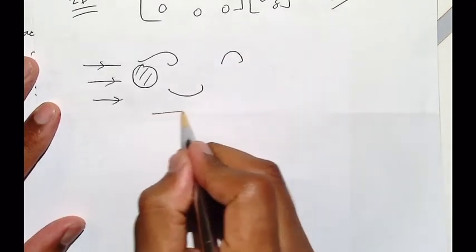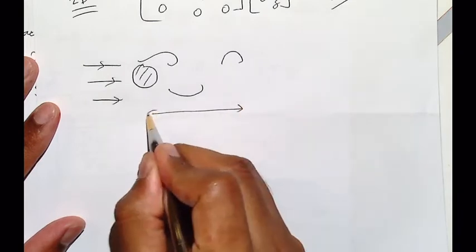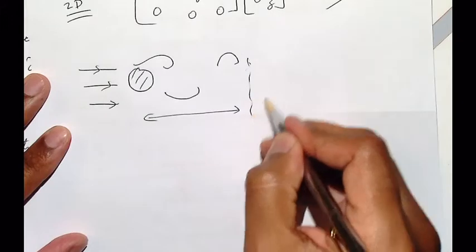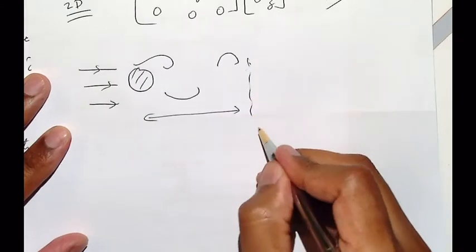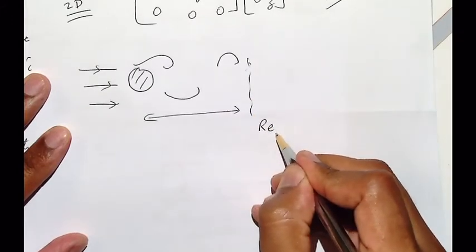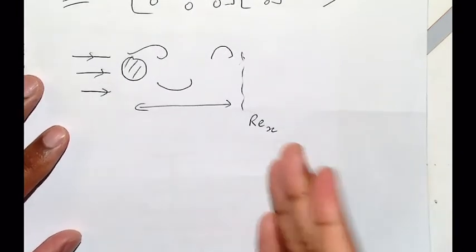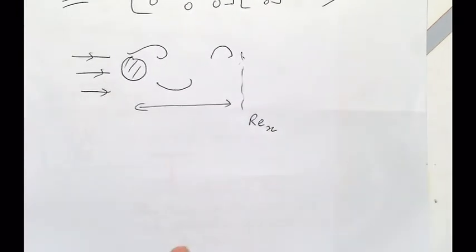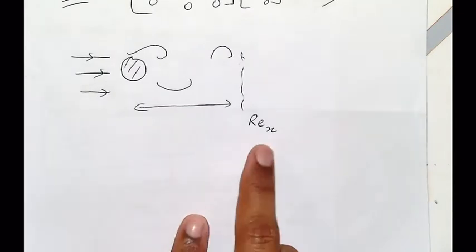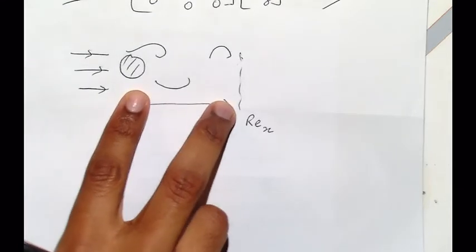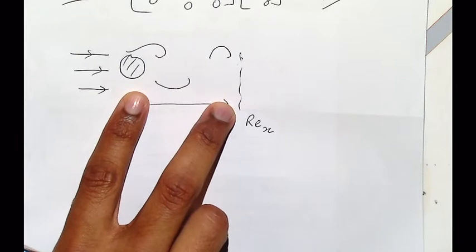And for some length, it will not be turbulent, but beyond some length it will be, because there's a local Reynolds number, Re_L or Re_x. Okay, so I think that's what you're talking about. If you go far enough in the wake, things will become turbulent, yes, because the Re_x becomes very high. Close to the cylinder, you will still have laminar flow.